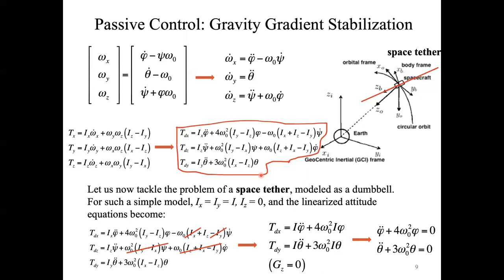Of course, the stability of the spacecraft is studied by assuming one of the main perturbations that you have, the gravity gradient. So the gravity gradient here will be used to stabilize the spacecraft and not to act as a perturbing torque.